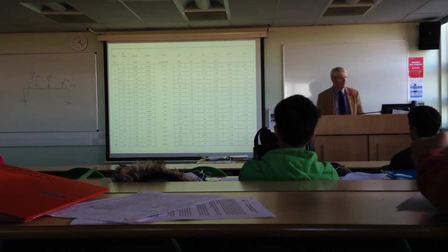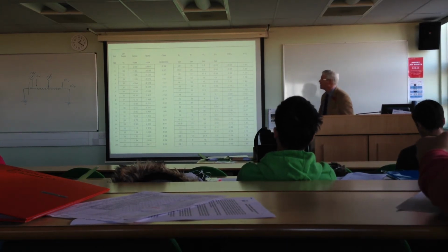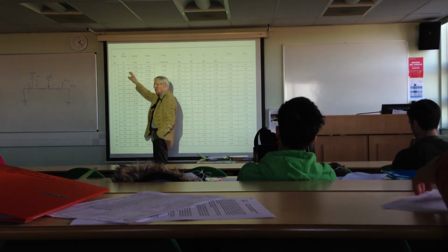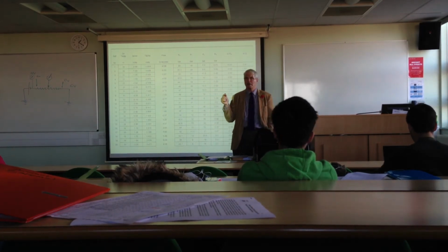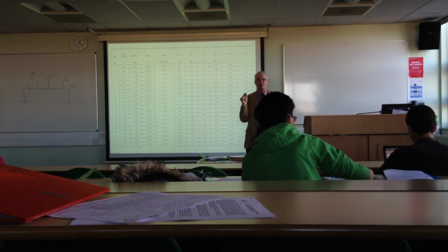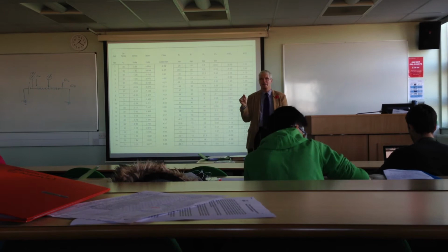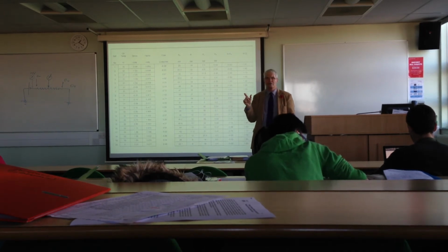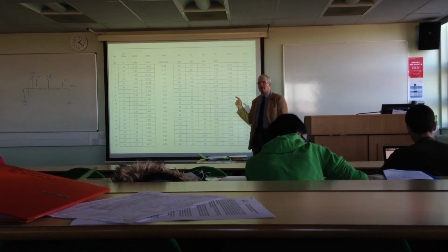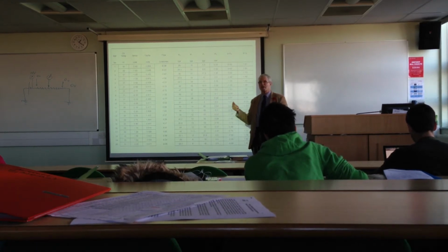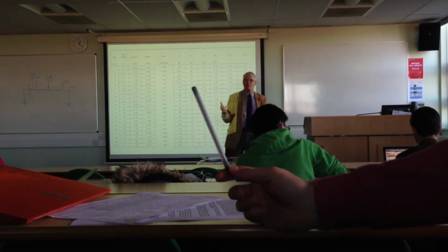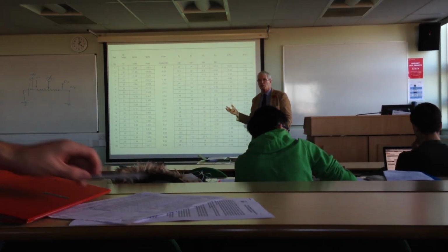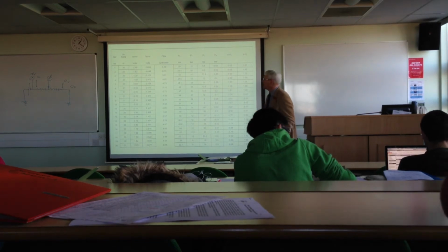So typical results, that's what you've got, I suppose, isn't it? We were being very good at recording temperature, and once it had stabilized, it didn't seem to change very much. But temperature affects the viscosity of the oil. So when you're running an experiment, it's a good idea to make a note of almost everything that could change or could affect the results. Because if the results don't come quite as predicted, in the discussion, you often want to find some reason or suggest some reason. When we look at that, we can fairly confidently say the temperature didn't change very much. We wouldn't expect the viscosity to have changed, so we don't expect anything strange to happen because of that.